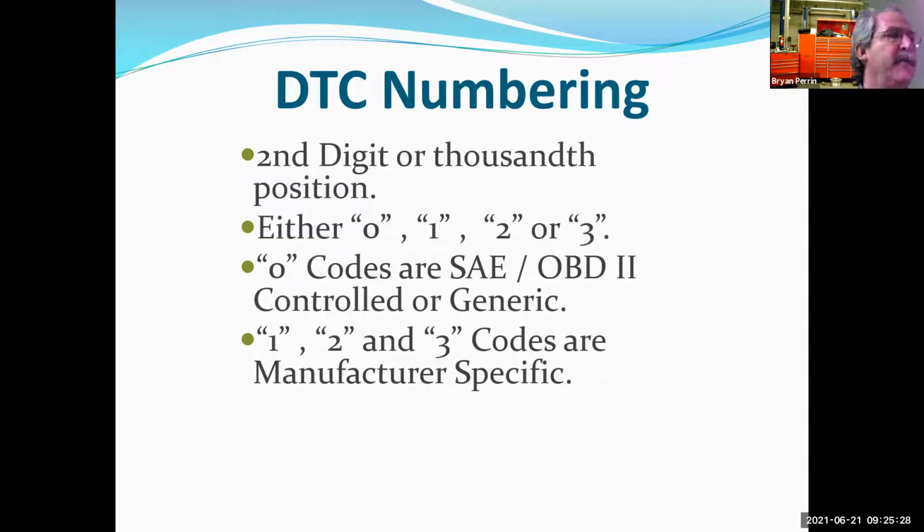If you can't find information on a BMW with a P2485 code, just put P2485 into Google and see at least what it says it is. That'll give you an area that has to be set in the code. It's not going to give you the exact code definition or what set the code, but at least you have some idea of what system you're working on at that point or what area it is. That's kind of a quick workaround. Some manufacturers don't share well.